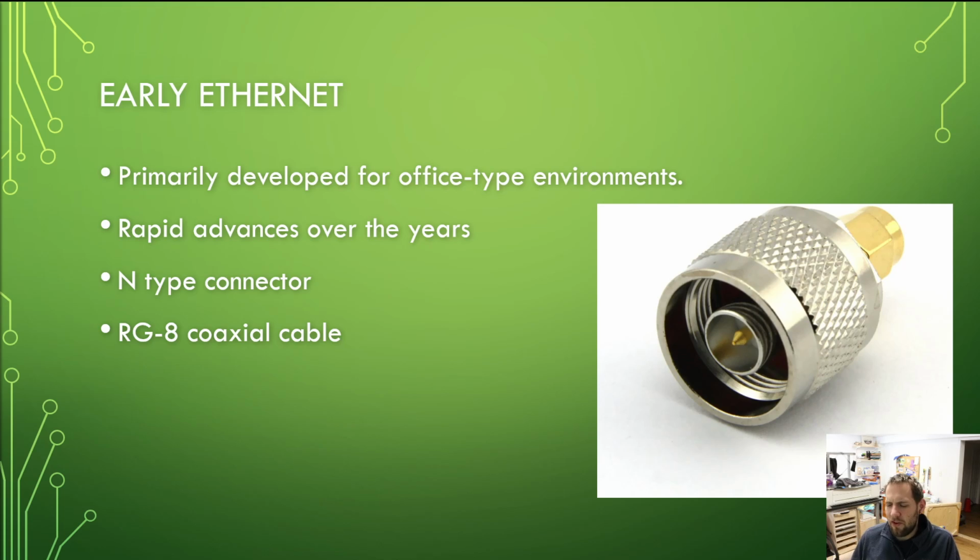You'd have the shielding continuing through to the connector, so we've got nice protection there. But a metal connector and its screws, the screw base, is one of the big keys to having a nice rugged connector, not something that's just going to pop out and be all flimsy. So it is a good connector in the long run for industrial environments, right? It will probably stand the test of time if you use these types of things.